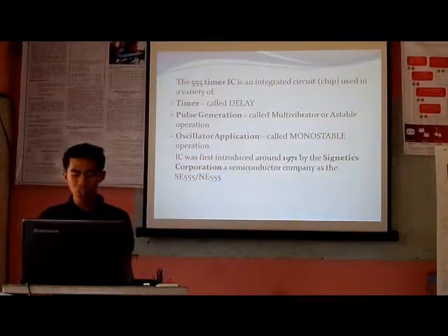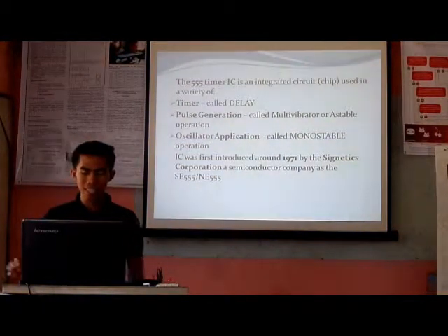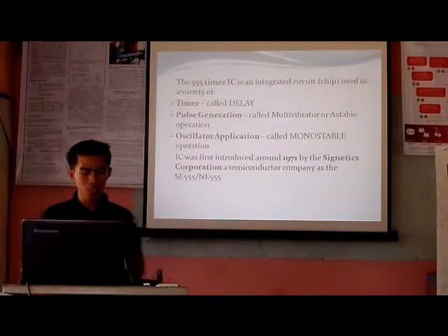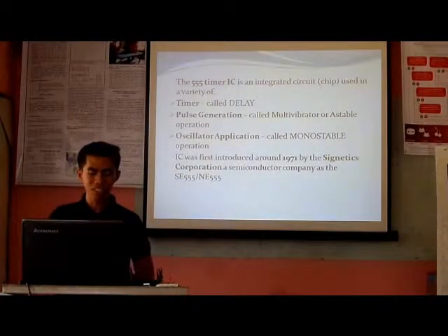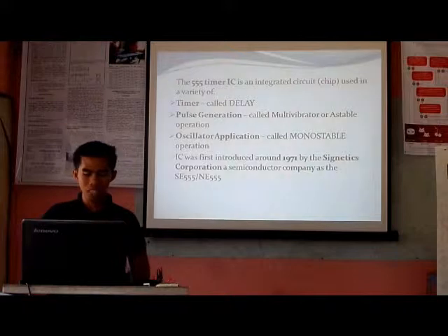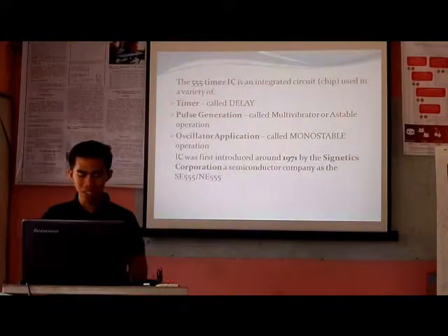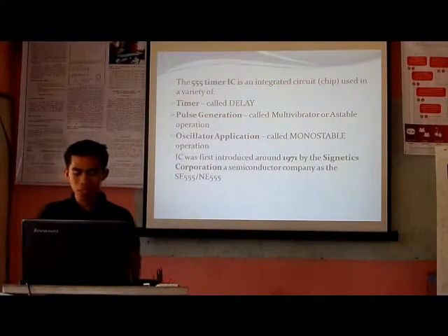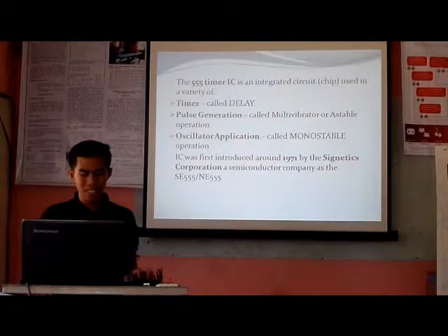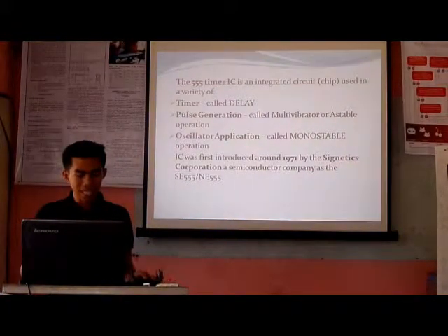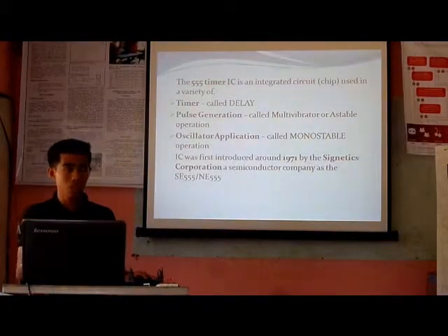Those parts should generally be included, however, because noise produced by the timer or variation in power supply voltage might interfere with other parts of a circuit or influence its threshold voltage.